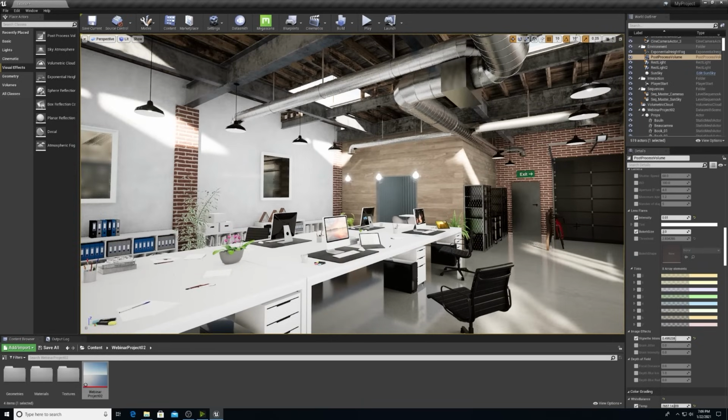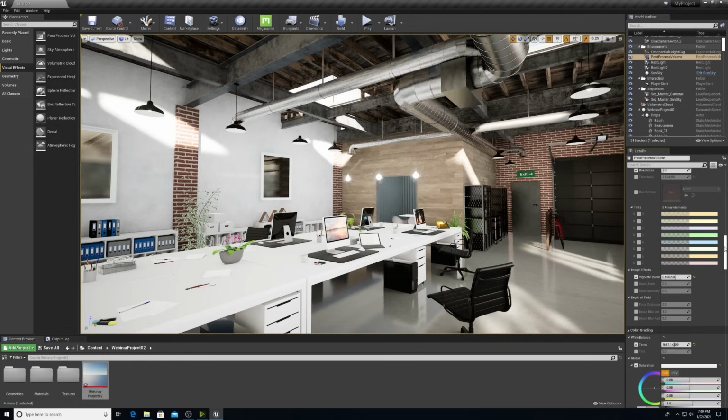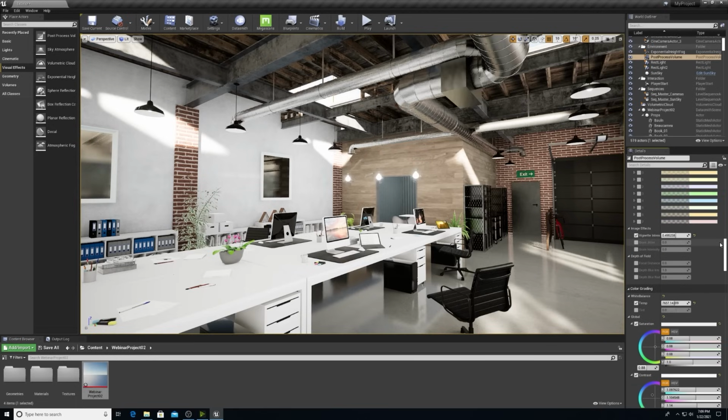Now, I'm going to take a look at the ray tracing features for a few different components here. Just a reminder, this is ray tracing for Unreal, which is a hybrid ray tracer that couples the ray tracing capabilities with our existing raster effects. This essentially means that this is a raster image, and we will be layering it with ray tracing. This will be more realistic, but also more expensive in terms of computational time.